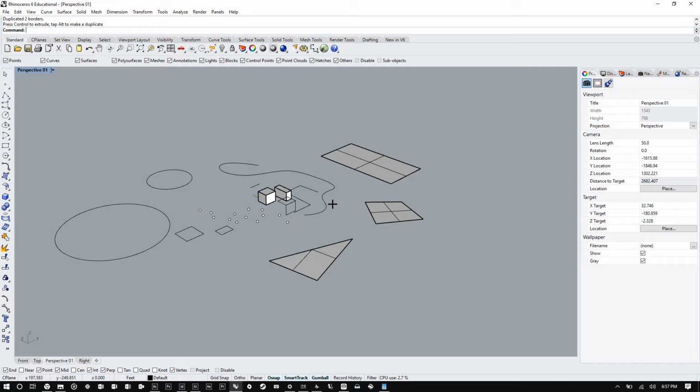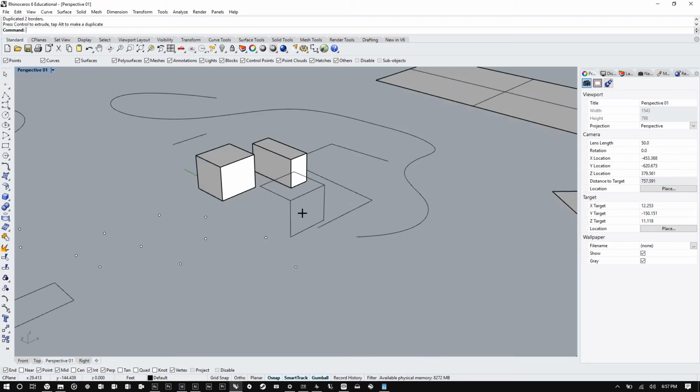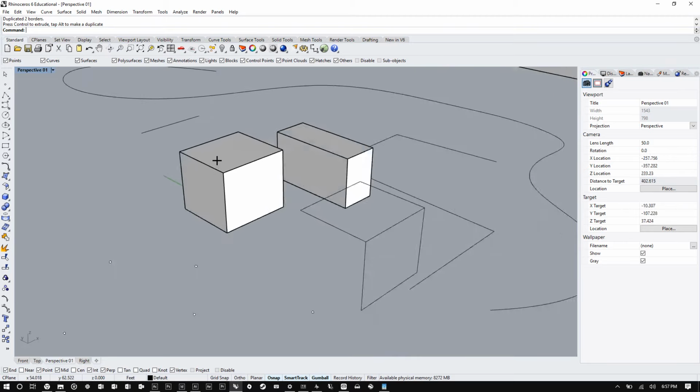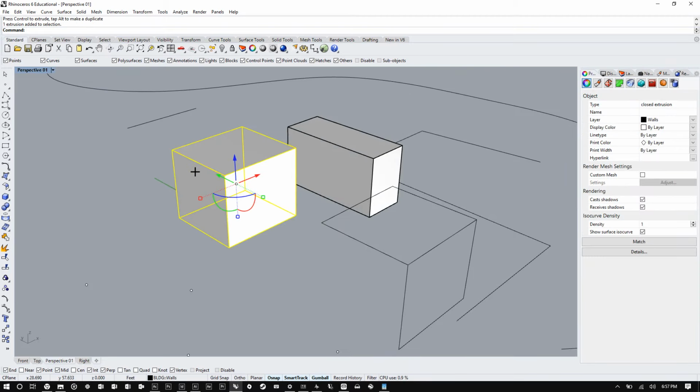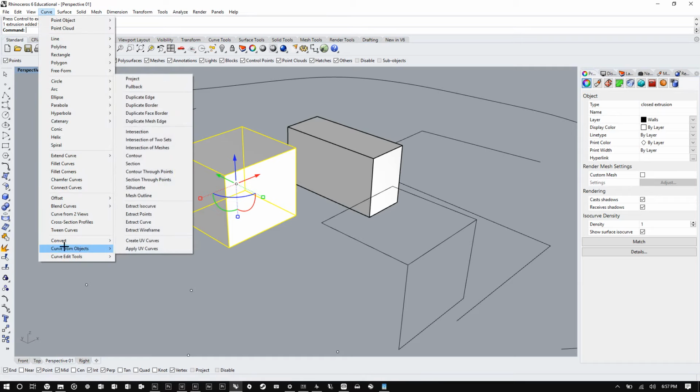Yes. Sorry, at one point you selected just a few curves. You usually select things that are part of an object already. Well, if they're already embedded in the object, you have to use a command to extract them. So right now, those curves do not already exist. They do, but you have to tell Rhino to give them to you. So that's why I initiated a command to get them. So curve from objects, and you can see a bunch of different commands.